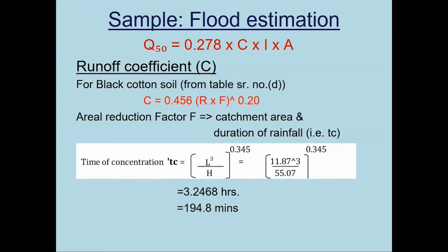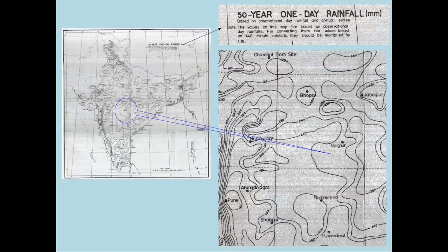As I have already explained in figure 4, where the graph is, if there is a rain beyond 3 hours, or if our catchment TC is more than 3 hours, still the ratio value will continue to be equal to the 3 hours value.